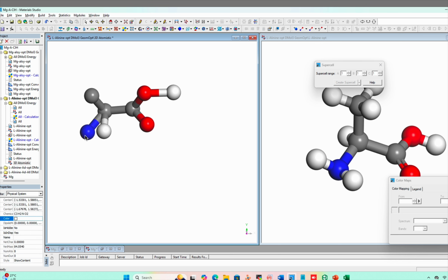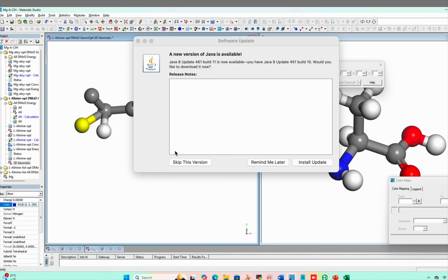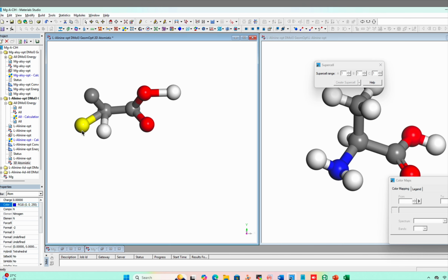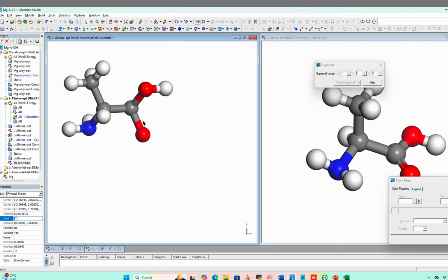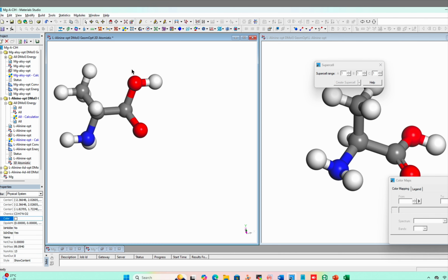And now here are two hydrogens with nitrogen, so right click, shift and alt button and right click, move it far away and select it, and then click on the hydrogen, so two hydrogens will attach to this. Then select the carbon, here is the CH3 group, and then clean the structure.